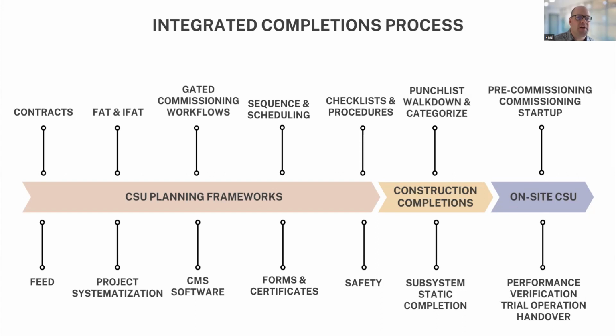So pre-commissioning and commissioning, what's taking place during each of those stages. You can think of pre-commissioning as the equipment level testing, the pump by itself. Commissioning moves more into the system level testing, where we're expecting the pump to be working with the motor, pipes, pressure gauges, everything working together as one subsystem, testing the process control narratives to make sure that the whole system is working together as a subsystem.